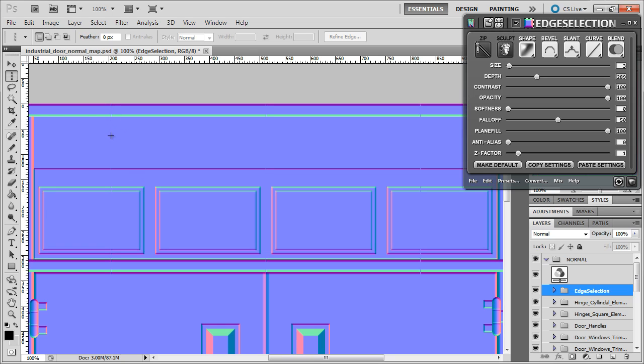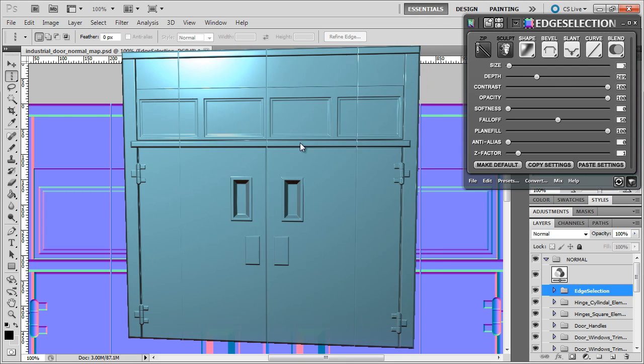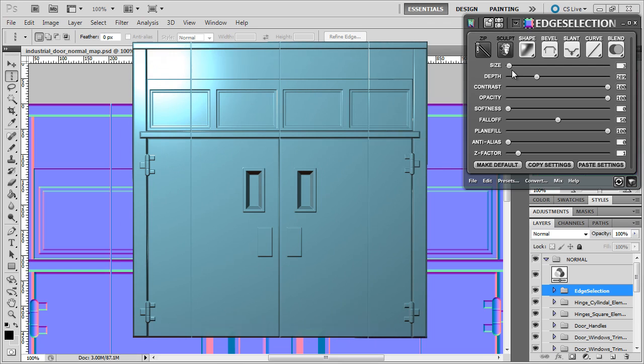But we can change that very easily with nDo. Right, so what we have to do is change the bevel to emboss, and now our lines will become much thicker. Right, but let's change the slant to down, so it actually looks like the lines are pointing inside the surface. Okay, and let's change the depth to maybe the maximum.